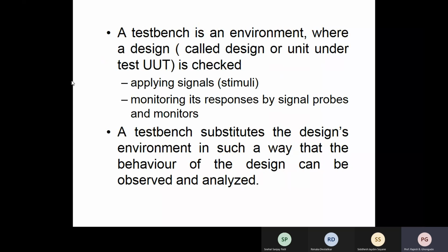So a test bench is an environment where a design, which we call here the unit under test, UUT, is checked. You check by applying signals, which we call the stimuli, and monitoring its responses by signal probes and monitors. Necessarily, a test bench will substitute the design's environment in such a way that the behavior of the design can be verified, that is observed and analyzed.